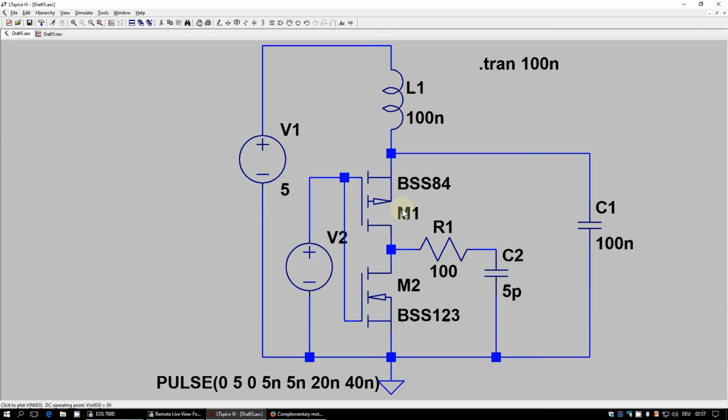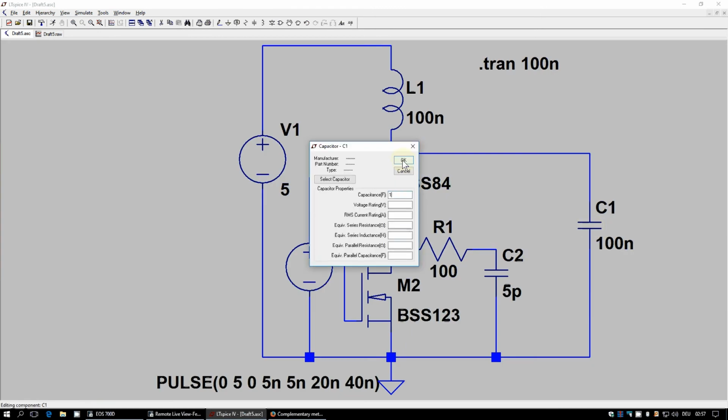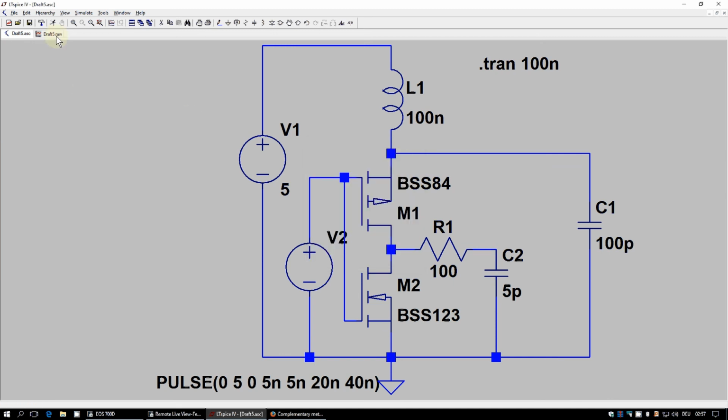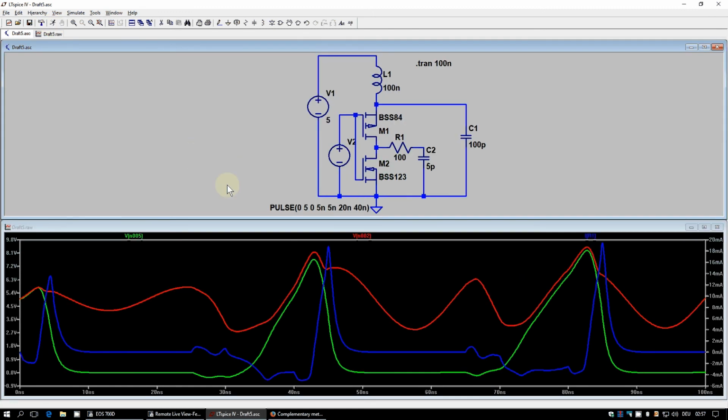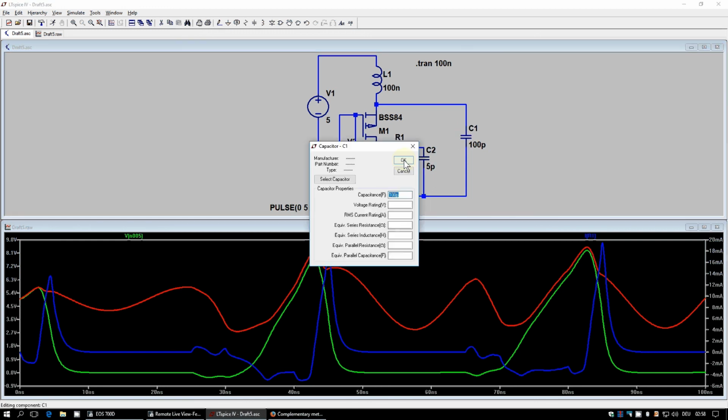So if we just take the wrong component and we take 100 picofarads, just a factor of 1000 too low, then we again have our problem. So 100 nanofarads, there is a reason why this is your standard value for a bypass capacitor for each single logic IC. And now there still can develop a problem.